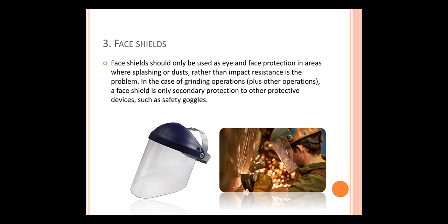Face shields. Face shields should only be used as eye and face protection in areas where splashing or dust, rather than impact resistance, is the problem. In the case of grinding operations, a face shield is only secondary protection to other protective devices such as safety goggles.